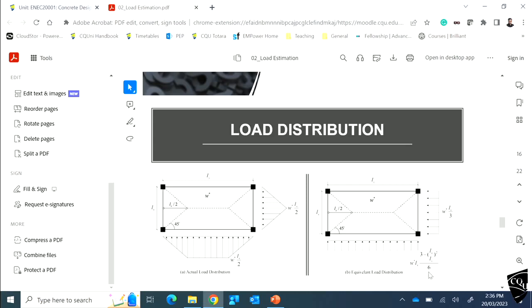When you calculate the loads, you need to calculate equivalent uniformly distributed loads. So it is better to show both diagrams and calculate the right side ones. For your project also you need that, because you need to design one of the beams. What you need is the right side load distribution for all the beams.